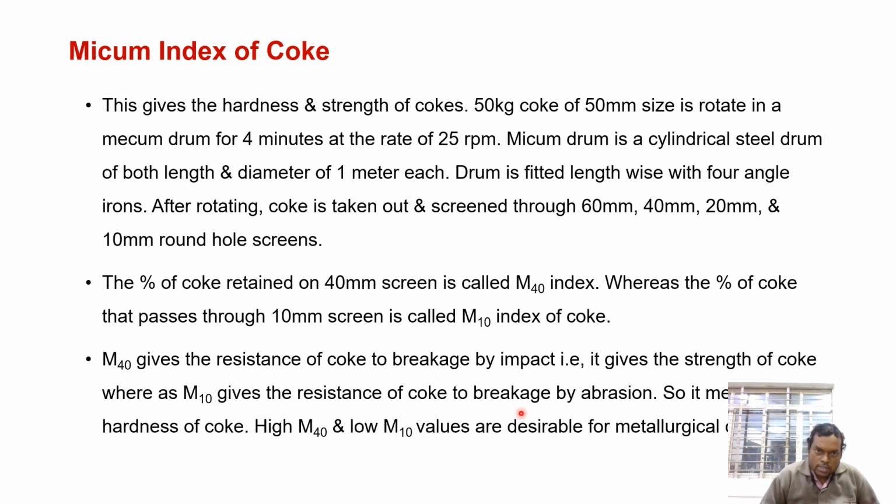What is shatter index? We have already discussed. Then Micum index: we have studied that it is mainly M40 and M10. M40 means the resistance of coke to breakage by impact. M10 means the resistance of coke to breakage by abrasion. So these things we have studied today.